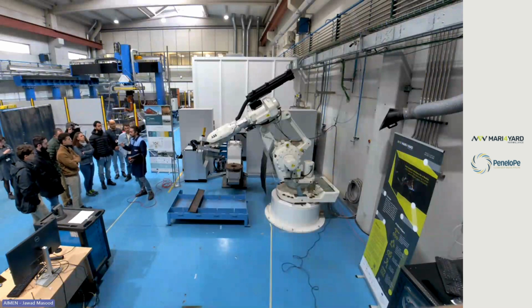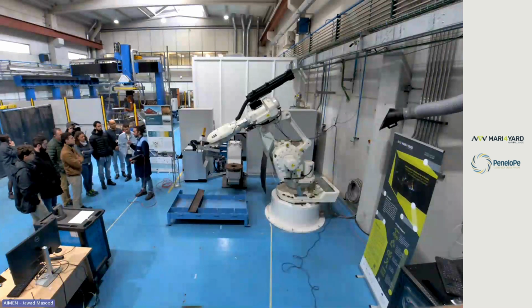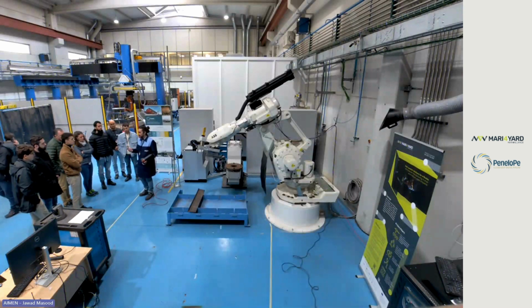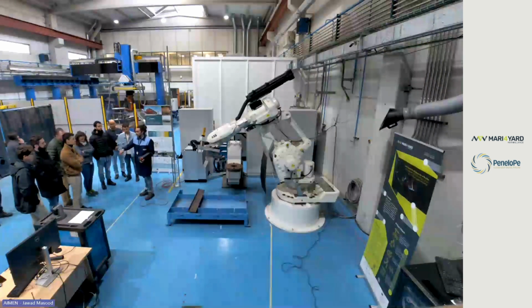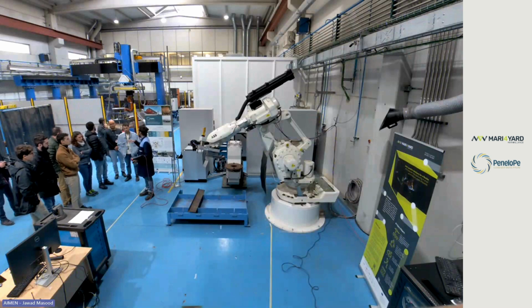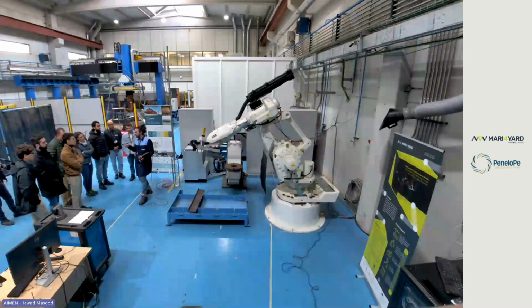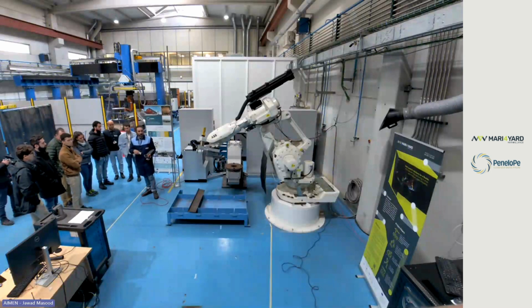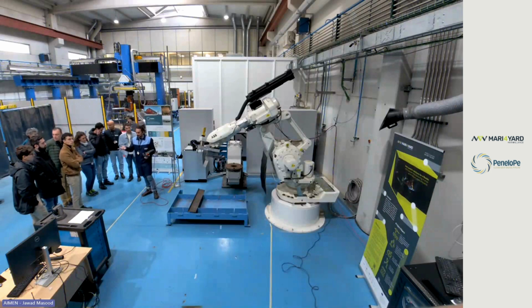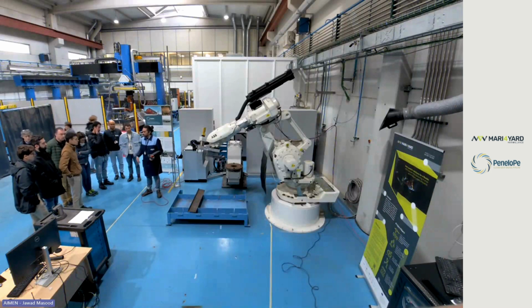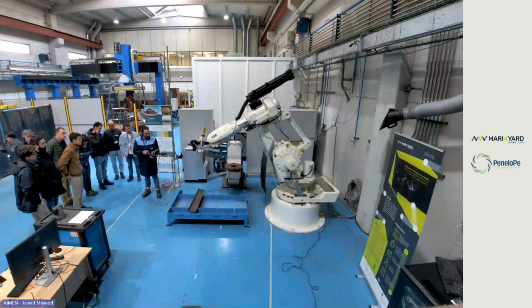Usually, as this is the first instruction, I'm going to create a move G instruction, not a move L. Move G has more advantages sometimes when you are working outside of the part, as I told you before, while move L is a little bit more limited. We have to know why and why not, but maybe in another training course more in depth.